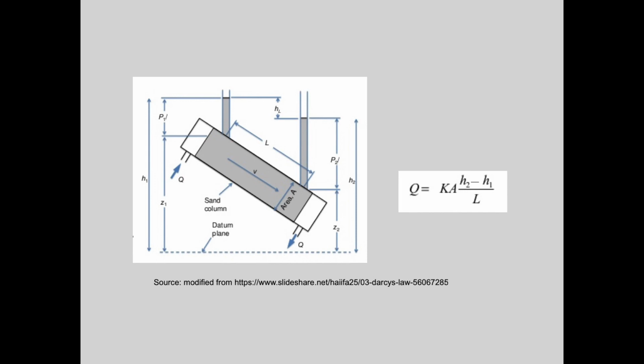Other parts of this equation that become important, when you see the letter K, this represents the permeability. It's a coefficient having to do with the permeability of the material inside of our experimental model. And then A, of course, is the overall area through which the water is flowing, and it is ultimately the total area of our experimental space, right? It's how much medium, in terms of square meters, is present in this experimental model.